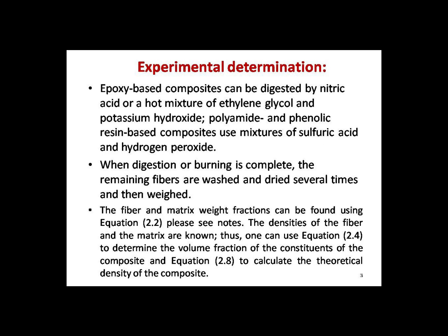Furthermore, we can discuss the burning test to be performed on epoxy based composites. Epoxy based composites can be digested by nitric acid or a hot mixture of ethylene glycol and potassium hydroxide. All these tests you can perform in your labs also, because I had shown you the different types of composites, the carbon fiber based composites as well as the nano composites which had carbon nanotubes and graphene infused in them, and you can easily perform the burn test on them in order to extract the carbon fiber from them.